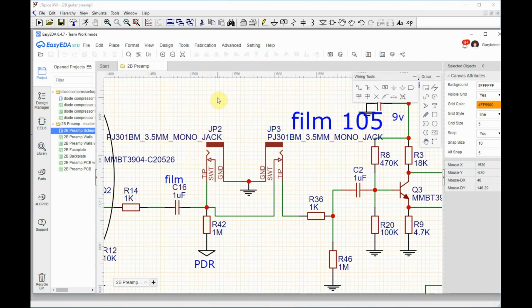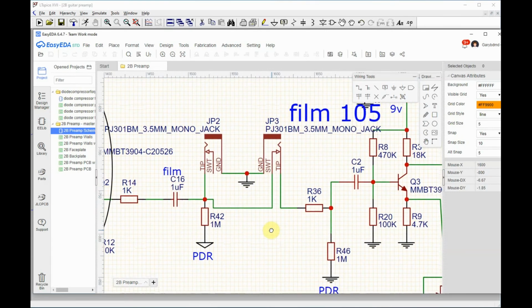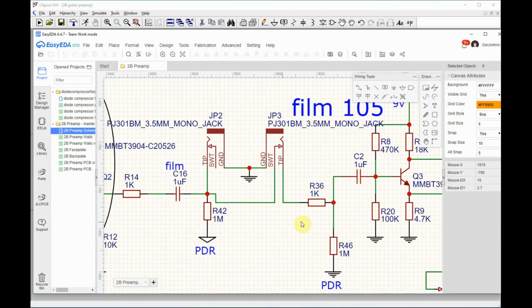I mean, if it's a pedal or effects unit or something, it's usually going to be 100K or more. So I just kind of use this in here, and I try to not go above 10 microfarads at all if I can help it, just because of the cost, and I don't like using electrolytic capacitors that much. So hopefully this is enough talking about the effect send and return. I think that's about all there is to it.